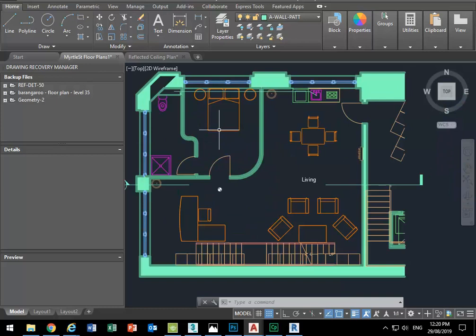And I mean they're cheap these days. They're like $80 or something, or even less. And the ones with batteries are fine, even though if you're doing a new build, they're supposed to be hardwired, so they're supposed to have their own electrical power supply. Most of them with batteries are for retrofits, for putting into an existing building. It's a fairly new thing, the hardwired requirement. I think it was 2016.